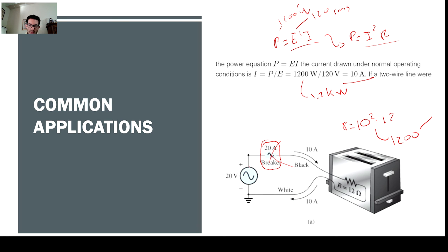But if you look at the circuit, you have your positive leg or your L1, usually called the hot line, going into your system, and then your neutral taking it back to the socket. In this particular case, they're telling us that this appliance, this equipment, probably only has two connectors. It doesn't have a third connector.